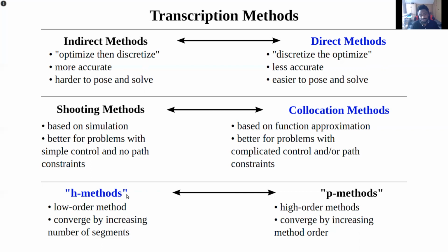And after you solve the NLP problem, that's the nonlinear programming problem, it returns a discrete set of states and actions. Given the discrete set of states and actions, it's now your duty to interpolate between these discrete points to come up with a continuous trajectory that you can then pass to your robot to actually execute. So the sequence is like this.